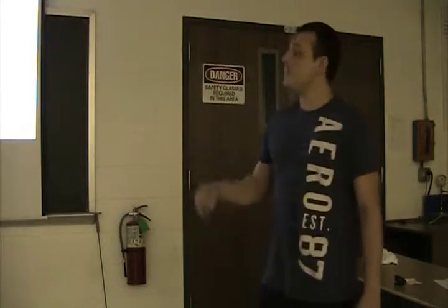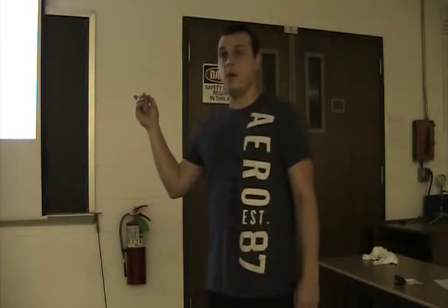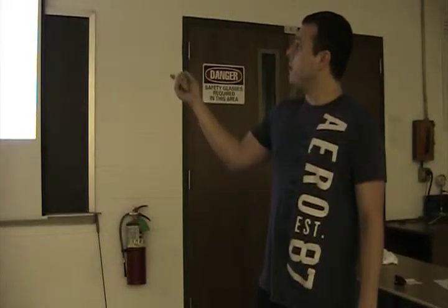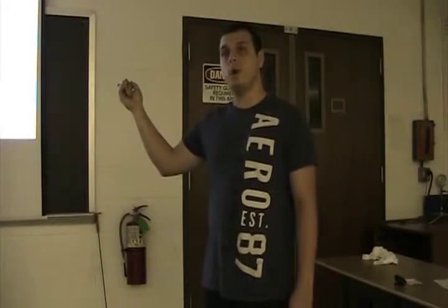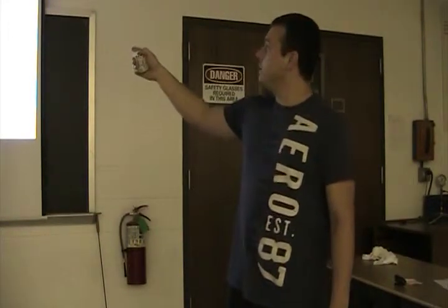So what you do is you place a suction inlet in the throat. When the high velocity, low pressure steam passes over the throat, it creates a suction. That way you can utilize this as a vacuum pump. It then discharges the secondary gas or fluid through the diffuser, so it expels it at a low velocity and approximately the ambient or exit pressure.